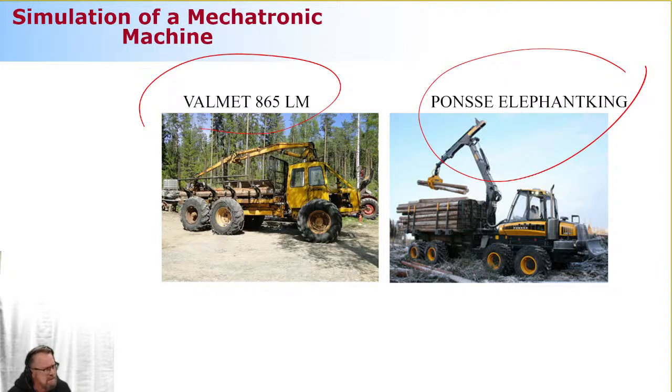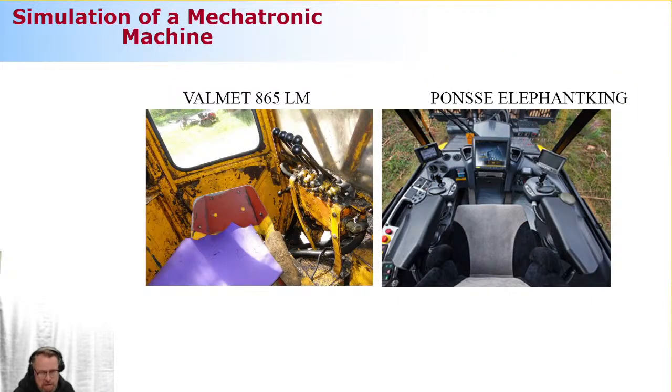Still, we have a diesel engine that is rotating the pump, that is then actuating the cylinders here. But there's a major difference when you look inside the cabins. This is how the cabin looked a little while ago. You see that there are mechanical connections from the shaft to the direction valves. Here, it's connected, but not mechanically. There are joysticks, and the joystick can help you with certain decisions that you can make. You can automate this. You can make this more pleasant. This one was how things were a little while ago, but the operation principle is still pretty much the same.